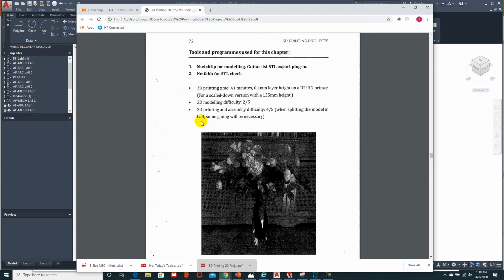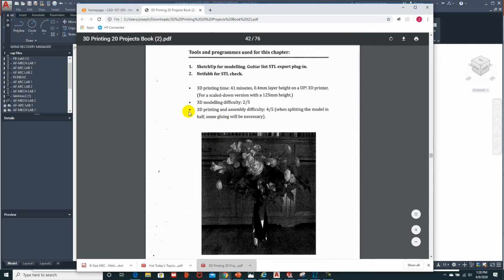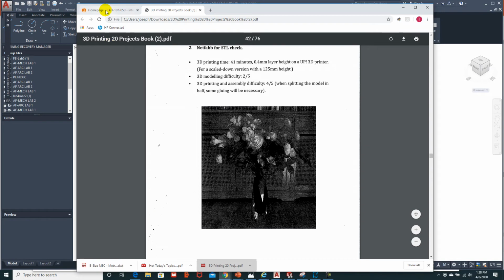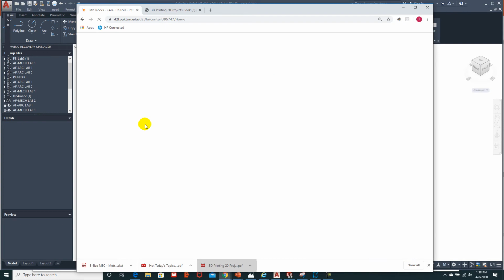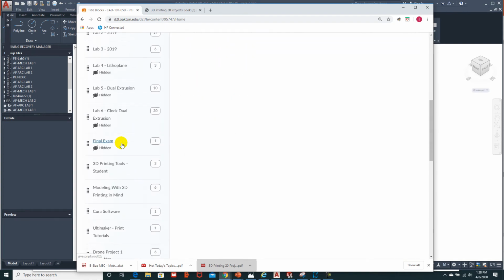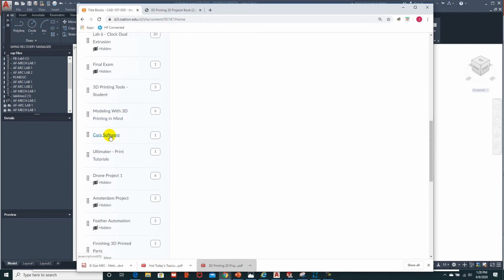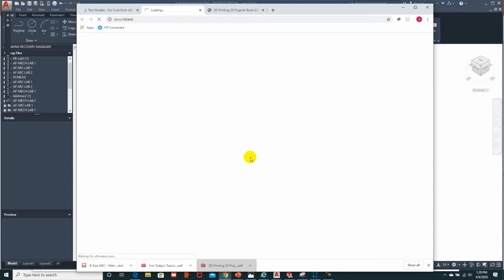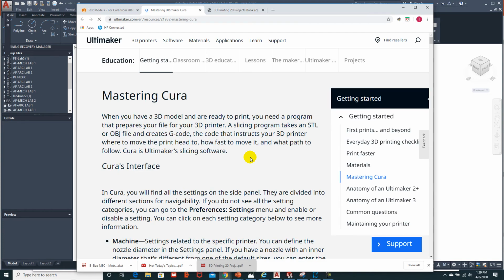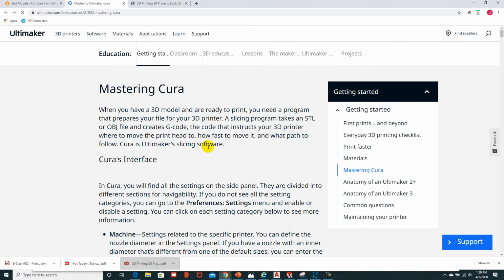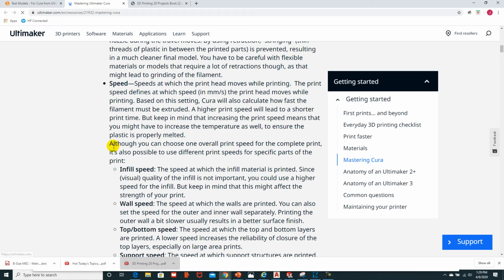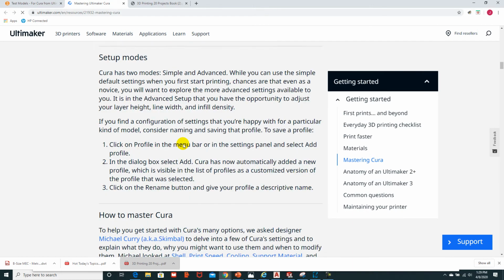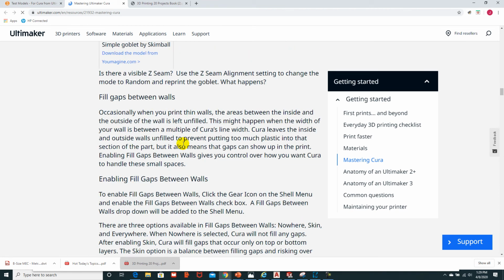We're going to use something called spiralized outer contour, which will allow the print head to move very quickly. And if we want to talk a little bit about the spiralized outer contour, we can come back here to Content, and there is some information from the software manufacturer from Cura on this mode. And if we click on this link, this guide is actually from Ultimaker, a 3D printer maker, and talks about all these different settings. And so they also give models that you can test them out for.